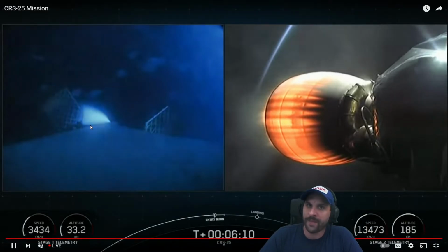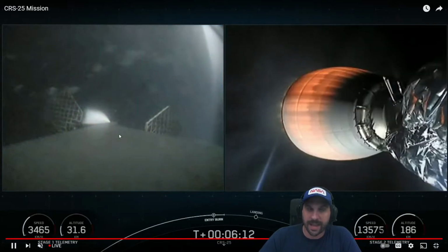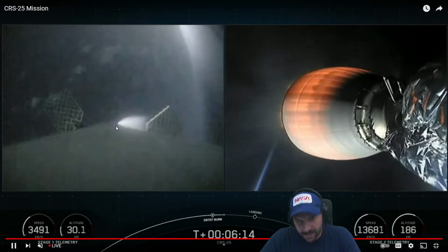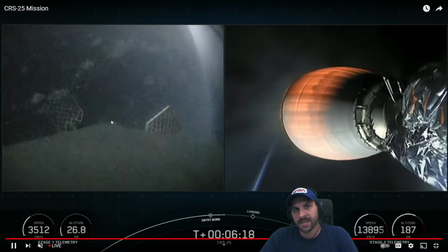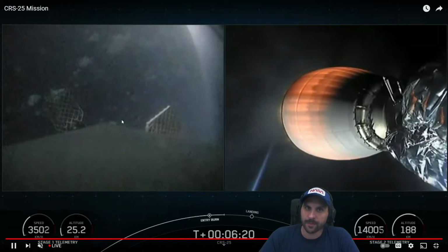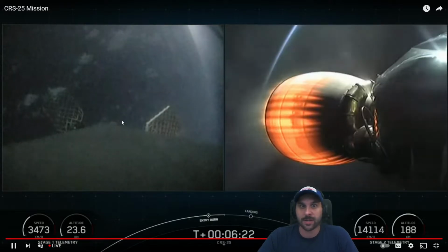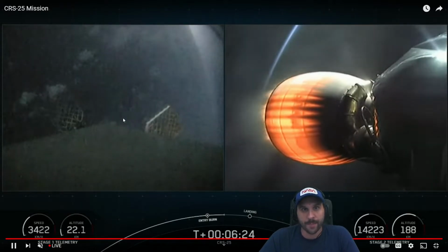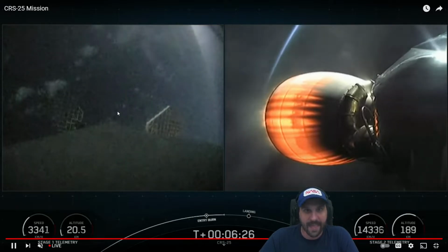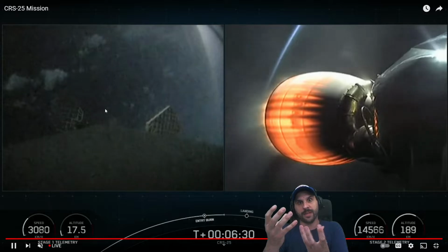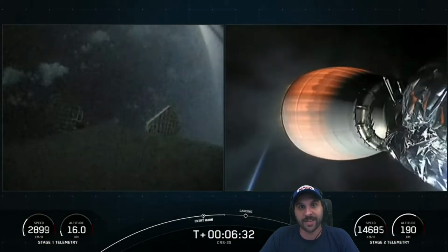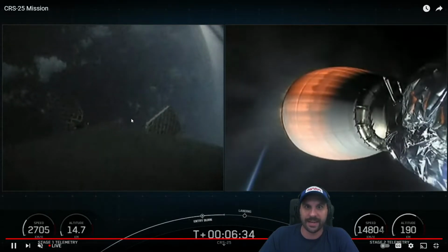And what Falcon 9 was doing there is not only slowing down, but they're using the rocket gases coming out of the engine to push the re-entry heating away. When stuff comes back from space, it starts to hit the atmosphere and compress the air so much that it rips the air molecules apart. That releases a lot of energy in the form of plasma. Plasma kind of accumulates like condensation on the side of the vehicle, right? Not on the side, on the business end down there.